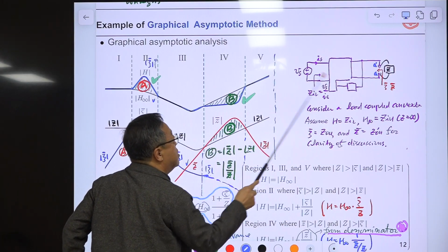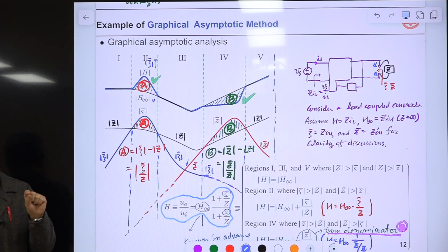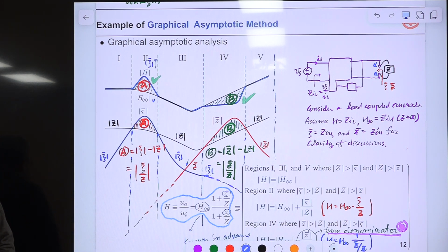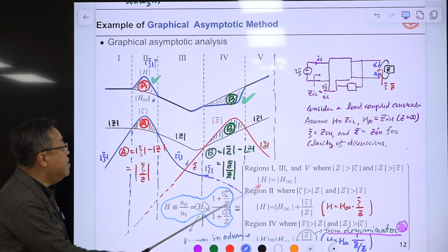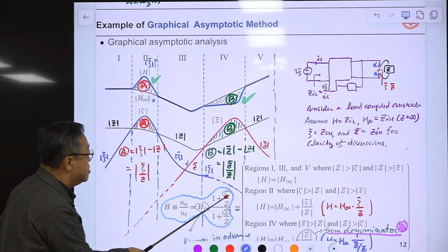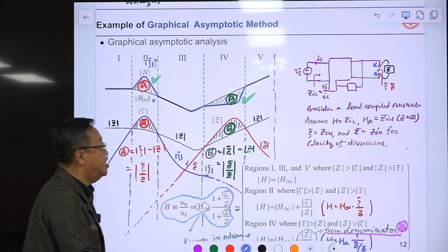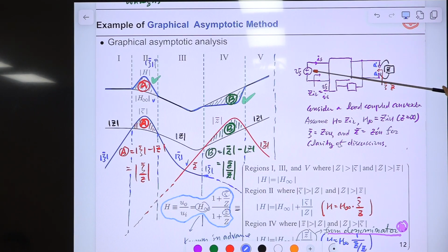So this is the input impedance of the uncoupled converter, but DC information of the output current is embedded in here. And this one, this zeta bar, is the null driving point impedance, which is the output impedance of this converter. We went through this.